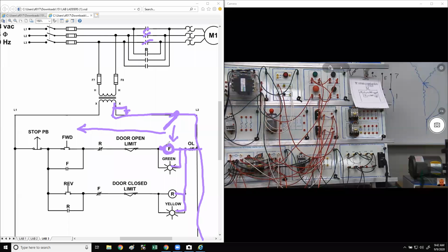What's your ladder diagram? Where am I checking? Like she said, the line side of the coil. Checking it right now, the way it sits, would I expect to see anything, even if the coil was good? No, we got to push the button. Very good. That's something else you got to keep in mind.